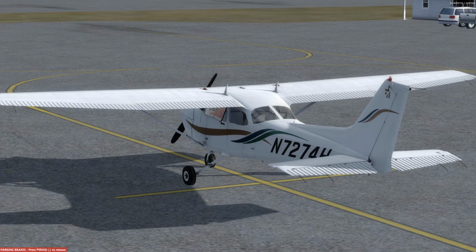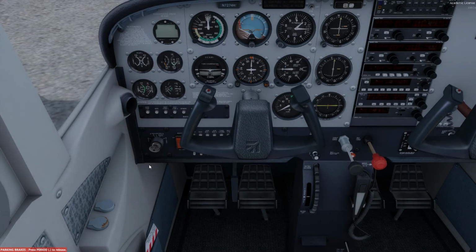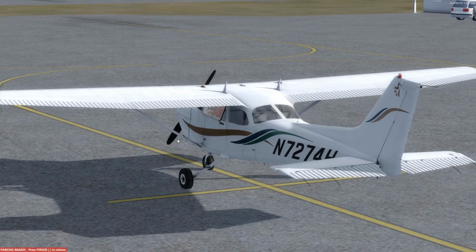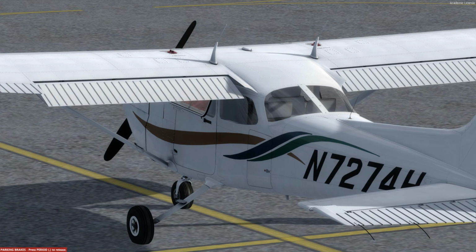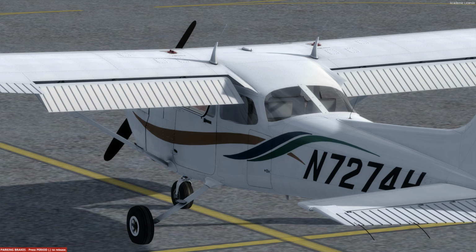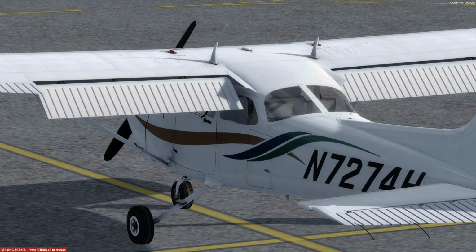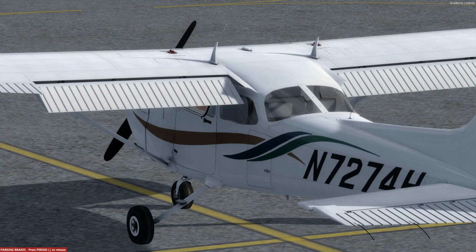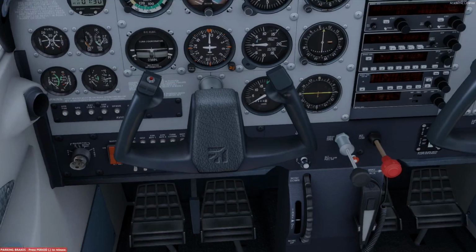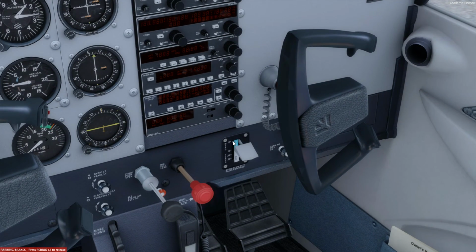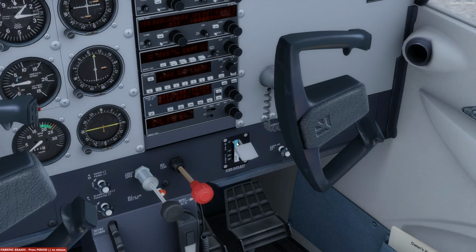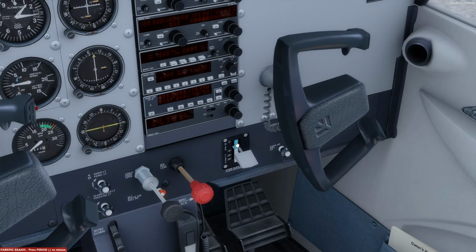And then on the inside trailing edge of the airplane are your flaps, and as you can see, the flaps go down at the same time. This will increase lift and also increase drag. And these flaps, and most flaps, will go down in stages like this that you can select. So in the 172, they're at 10, 20, and 30 degrees. So you can go into the cockpit, and you can hear them moving, and you can see the position indicator move. So if you select the first notch, 10 degrees, see it move, and you can select 20 and 30, and back up.